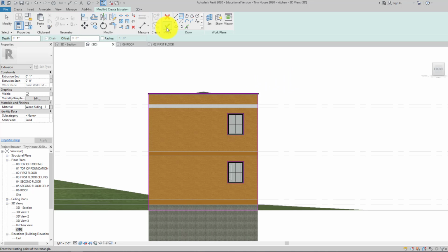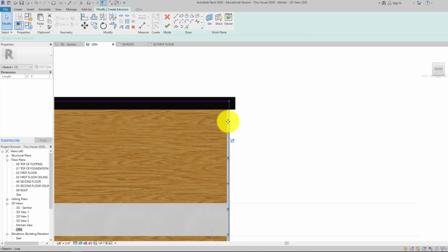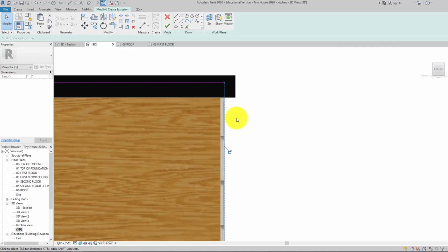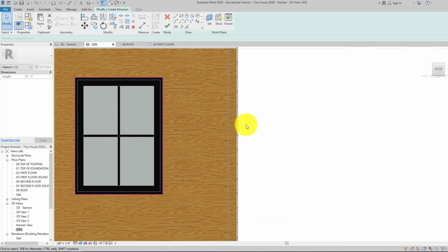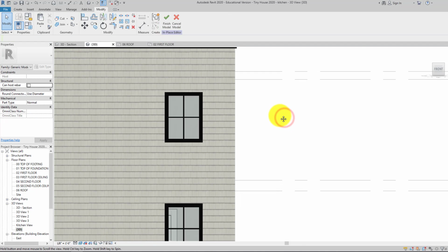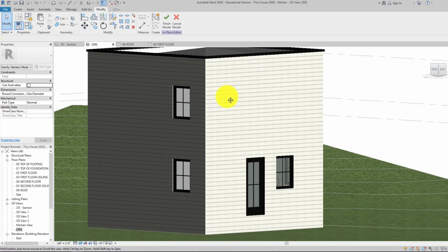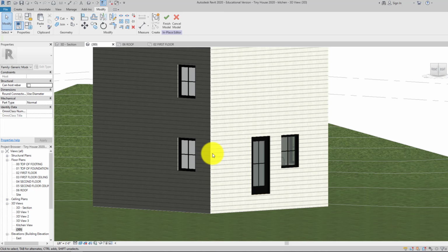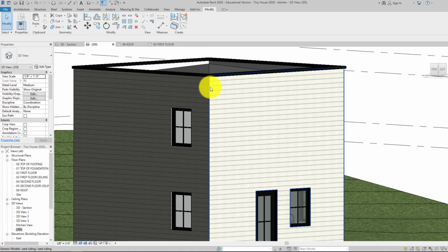And then before I click the check right here, you can see how it's not overlapping. One of these edges should overlap, even though there probably should be some sort of trim, or we could have gone on a crazy angle from the top view on a 45 miter and done some things. We're not going to get that crazy in there. So I'm just going to bring that over like that, and now I'm going to hit finish. I hope these line up. And they don't. So we need to fix that somehow. So I'm going to finish model, and let's see how we can fix that.